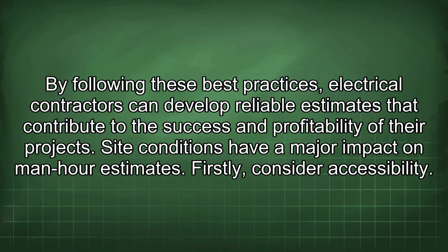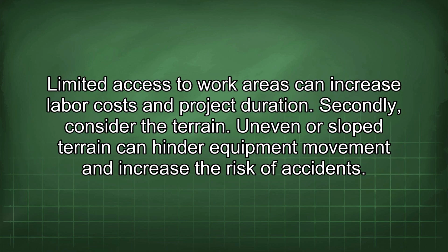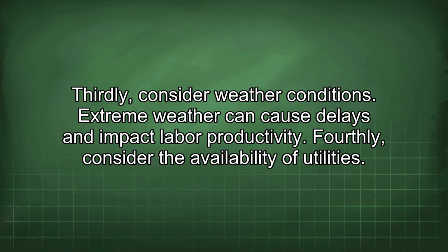Firstly, consider accessibility. Limited access to work areas can increase labor costs and project duration. Secondly, consider the terrain. Uneven or sloped terrain can hinder equipment movement and increase the risk of accidents. Thirdly, consider weather conditions. Extreme weather can cause delays and impact labor productivity.